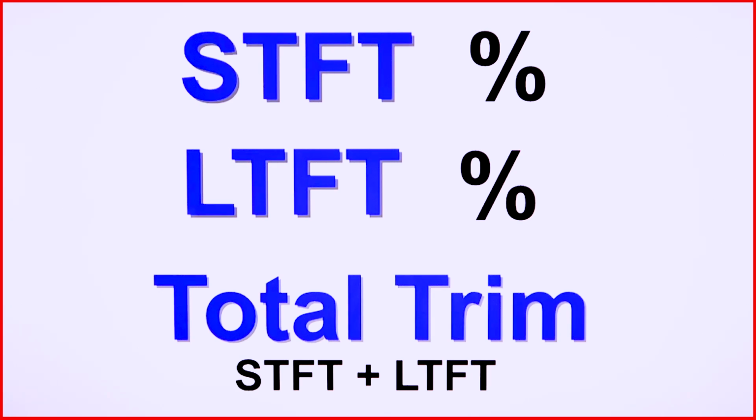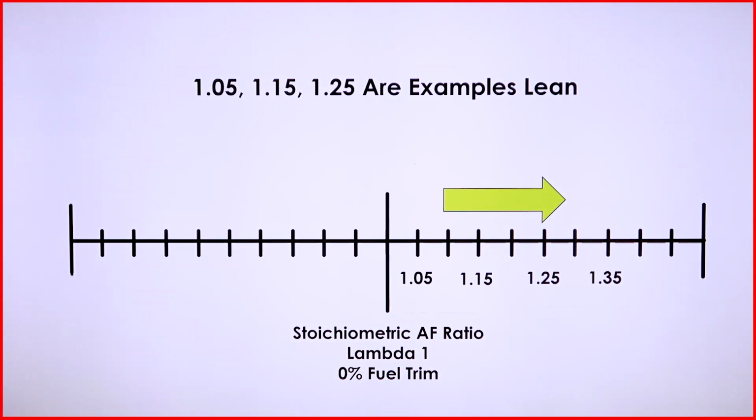But as long as it's within a plus or minus 10% window and not setting any trouble codes, that's the most important piece here. No trouble codes are set, you should be in good shape. So let's take a look at Lambda.